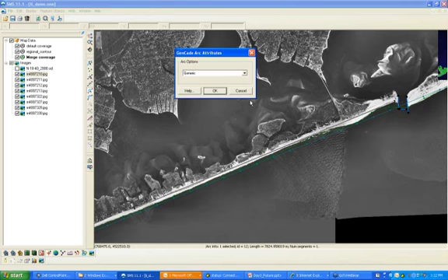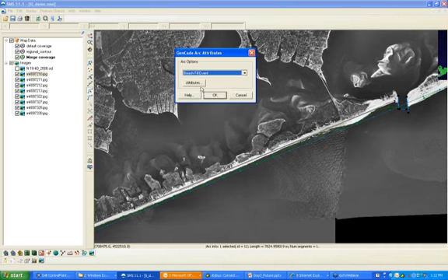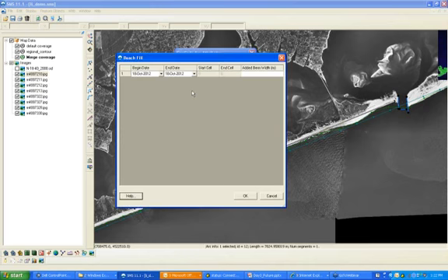Then I'm going to go to Select Feature Arc, double click, and I'm going to open my arc attributes and call this a beach fill event. I'll go to Attributes, and one nice thing that you can do is, for an example where you have the same beach fill but it's renourished, we can actually enter multiple beach fills for one arc. So for this case, the first beach fill starts on April 1st, 1984, and it extends till May 31st, 1984. So I'll enter that information.